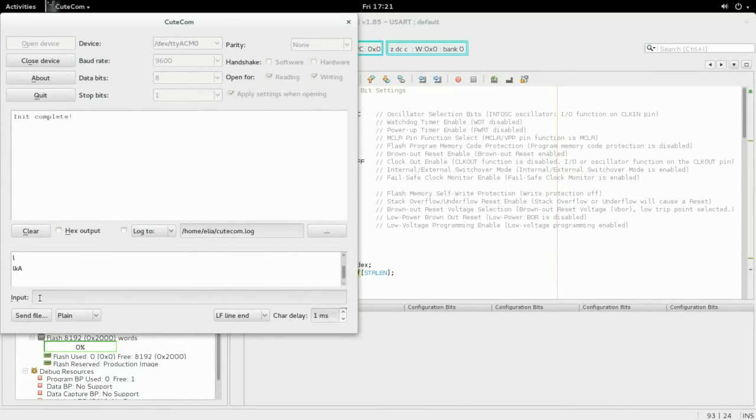And then we can also send stuff to the microcontroller, and when we hit enter, the terminal program will append a new line character. So if we just type hello, then we'll echo back hello. We could also do something like tuna. Well, that's rather interesting. What you can see is that it sent tuna, and then it also sent O and the exclamation mark.